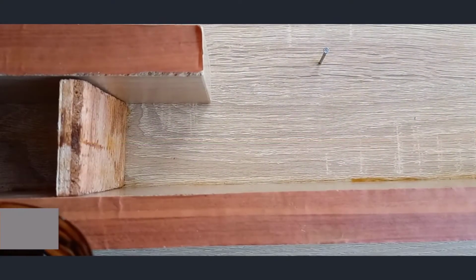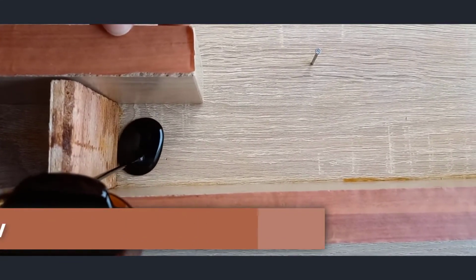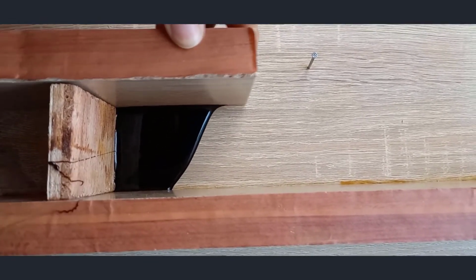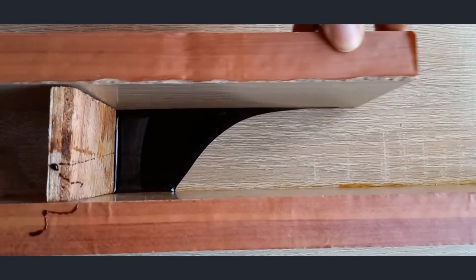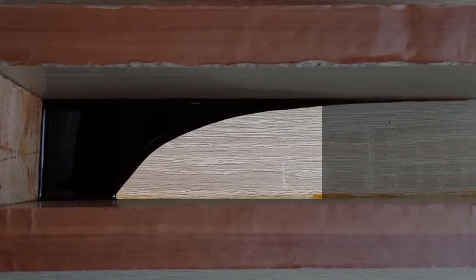Up next is the Couette flow. In this phenomenon, the fluid flows by the movement of the upper wall, and the mass is constant. As you can see, the flow of the fluid is being caused by the dragging of the upper plate, and this forms a right angle triangle shape.